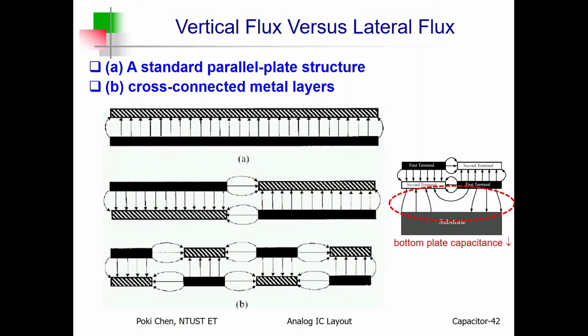for such kind of vertical flux versus lateral flux, you can see from the very beginning, this is for parallel plate capacitor. You have the top plate, the bottom plate. You depend very much on the vertical flux. All right. So if you cut it into two halves, then the lateral flux will show up, and also the vertical flux will be reduced.